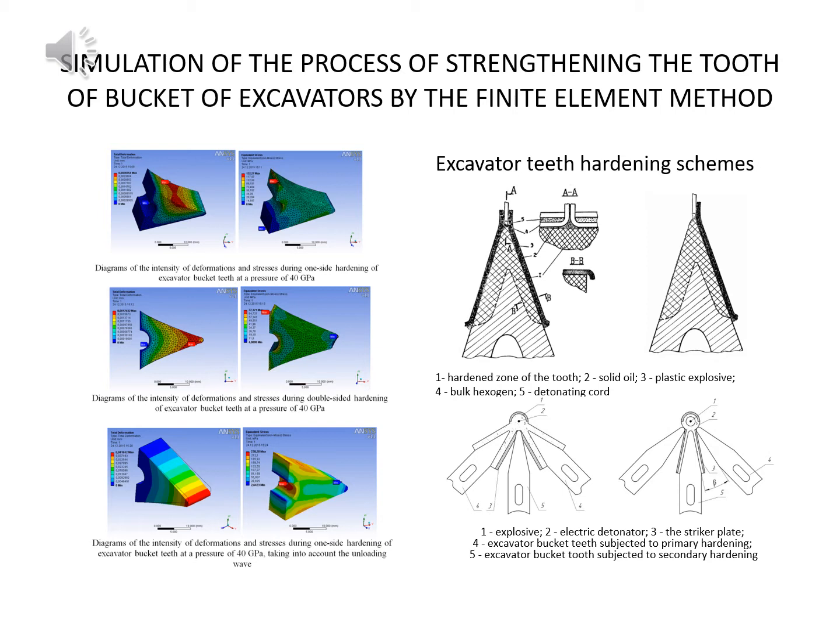The technological parameters are the following. Detonation velocity D, which characterizes the type of explosive charge. Dimensionless welding parameter r, the ratio of the mass of the explosive to the mass of the driver, such as plate or pipe. Distance between the welded workpieces, welding gap h.